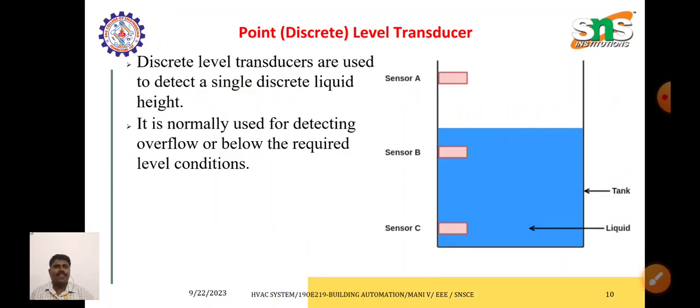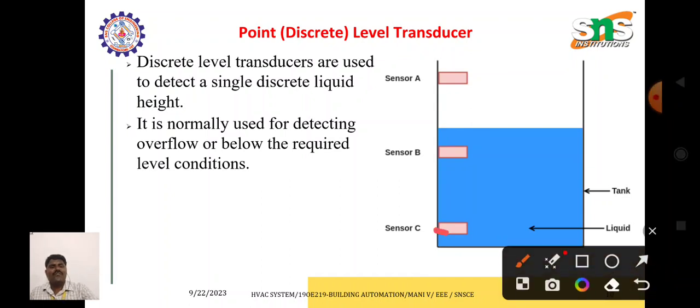And next, the point type, or it may be called the discrete level transducer. Here we keep a few sensors: one at the topmost, one in the middle, and another in the lower section. Once the water level touches sensor A, we can imagine the water is full. When the water reaches sensor B, it gives the information that the water level is 50%.